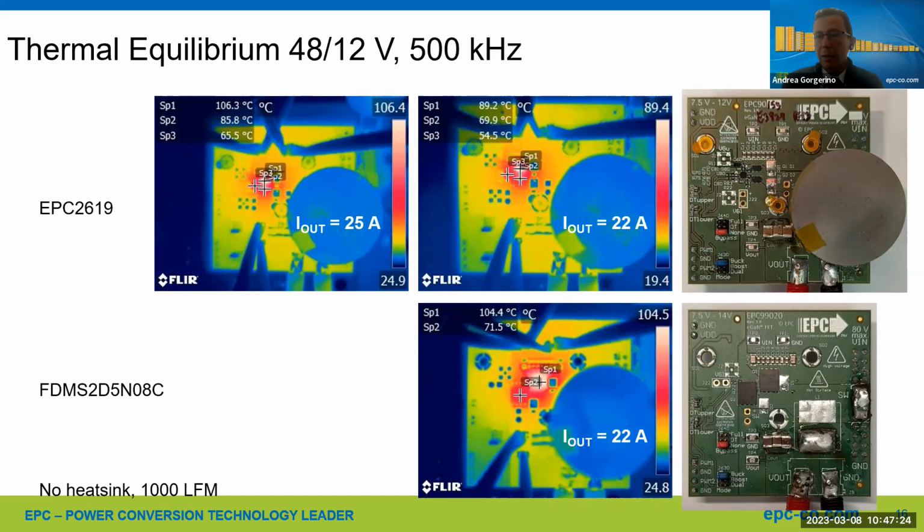But you can also use more traditional silicon gate drivers, as long as they meet the things I mentioned before, which is basically the ability to control that voltage to around 5 volts and not over 6 volts. That means appropriate undervoltage lockouts, and yes, you have to be careful with dV/dt immunity, because if you want to switch fast, the gate driver needs to survive.